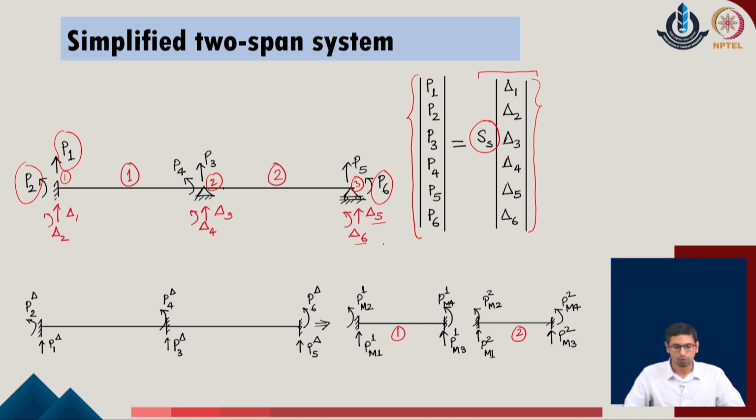Now, in order to identify the stiffness matrix of the given system, as we have already said, we one by one release all the degrees of freedom in the given system. So, we will initially release, say, delta 1, and corresponding to the release of delta 1 we will define what specific deformation the system is taking. Once we release this delta 1 value, we realize that at the respective positions forces will be generated. We can call them the forces due to the delta 1 contribution in the given system.